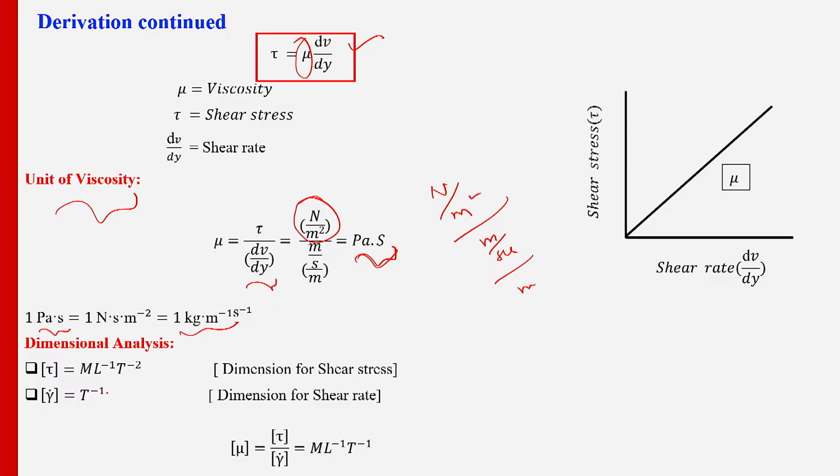In terms of dimensional analysis, that is different, maybe we will discuss that later. Whenever mass is there, we always write M, whenever length is there L, whenever time is there T, and temperature similarly. So, the dimensional analysis for tau is different, we will discuss it in some later classes. Here this is the shear stress, then the shear rate. If you solve the shear rate, we will get time inverse, so we can write it as T inverse. Finally, the viscosity units here, ML.